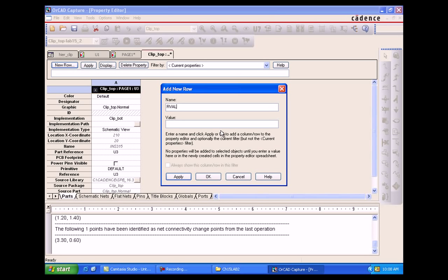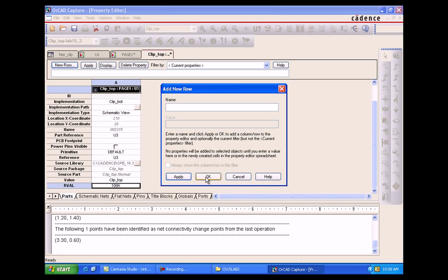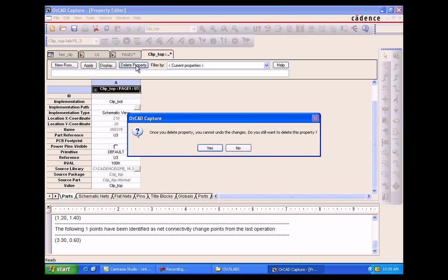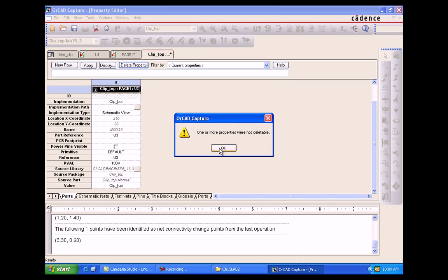Because we are using subparameter rval for all analysis, we have to add rval to every block and make the initial value of that one 100k. So for U3 we have 100k of rval. Apply to the circuit.